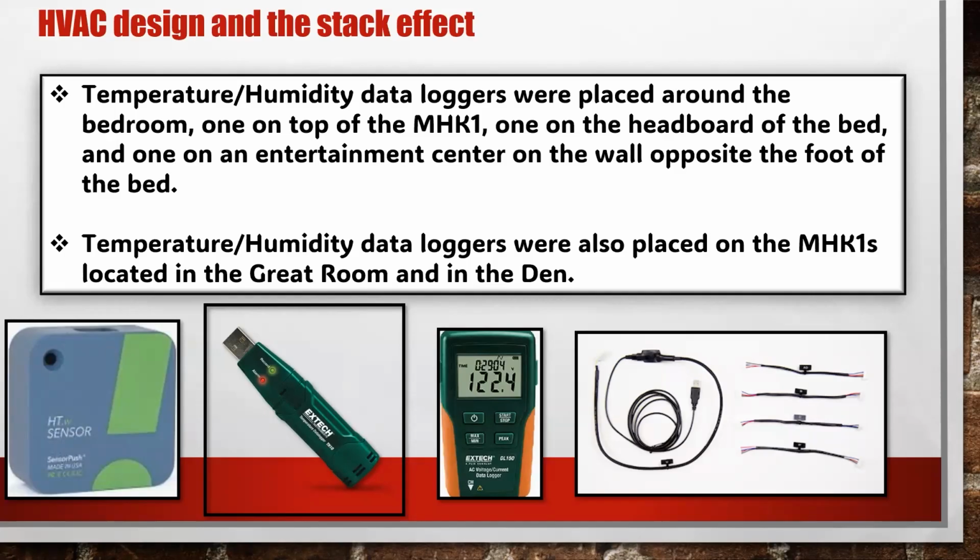Oh, okay. So I was just thinking it's positively shutting off the fan, or with more accuracy. But still going to have that hot coil. And that coil protection will come on even with the resistor cut, or is that not happening anymore? Are we risking damaging the equipment? That is still going to happen. The only way you can stop that from happening is turn the unit to off. If it's in the off mode, it won't do that.